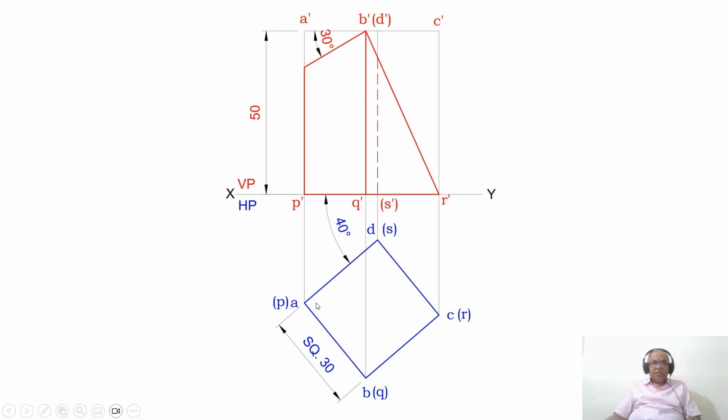and this point as A. Using the protractor with D as center, with reference to AD, draw a perpendicular by 90 degrees. Similarly, with A as center, again with respect to AD, measure an angle of 90 degrees and then draw a perpendicular to AD.